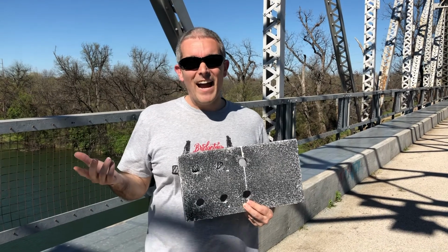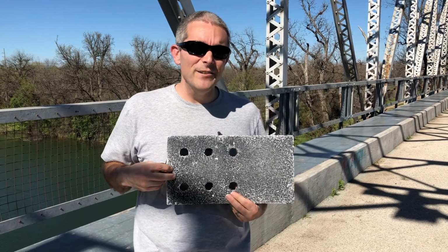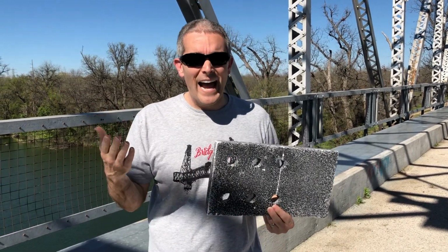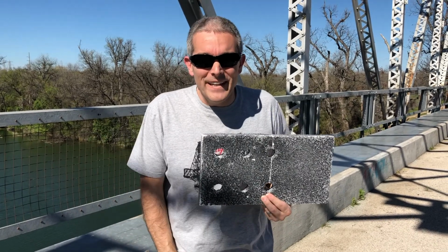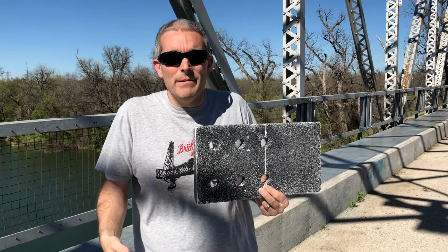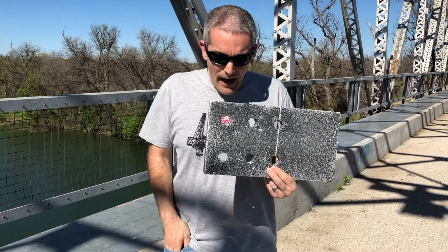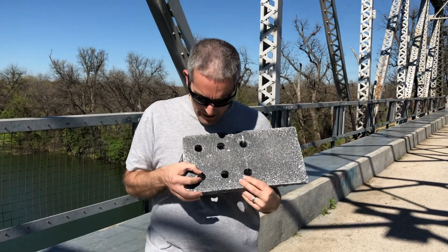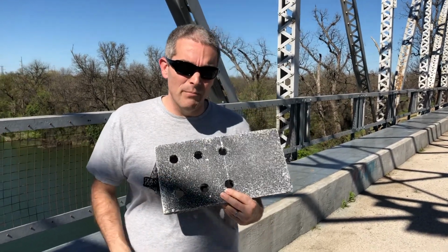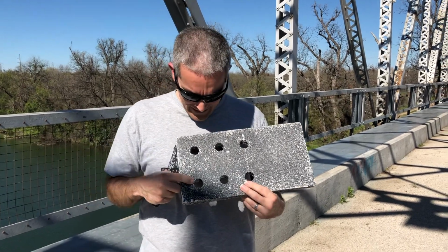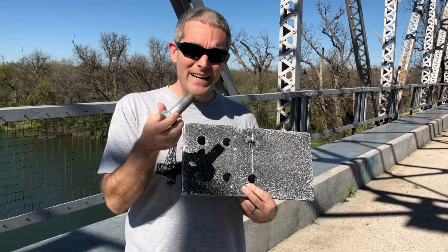So I just described what we're going to use as the effective diameter of the hole. And I just want to remember, as engineers, we can't forget to be practical, right? When we come up with the design distance for this bolt diameter, we can't just go with the bolt diameter. For instance, I made 1-inch holes into this particular member, but this is a 1-inch bolt.